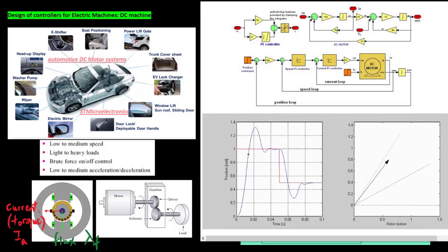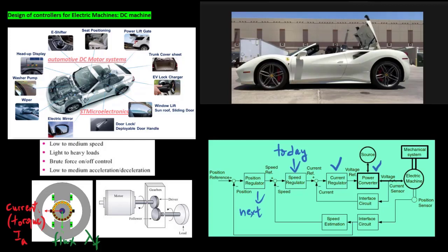Hence, if the load torque, inertia, and friction are given, the speed can be regulated by the torque of the machine. So, to control the speed in the speed regulation loop of an electric machine drive system, the torque of the machine should be controlled, and the output of the speed regulator is naturally torque. In this video, the design of the speed regulation loop is discussed.